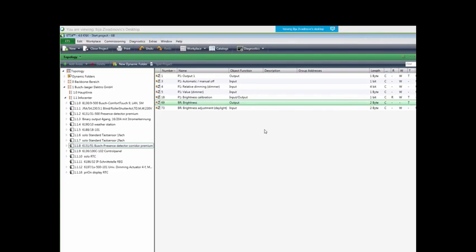What you can then do is send over the bus monitor, over this object, or you can also use a group address, to send the new value of 410 lux. Then the presence detector will internally and automatically calculate the brightness with the new given value.